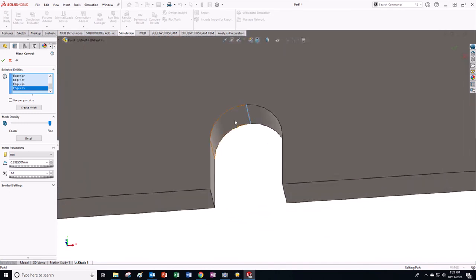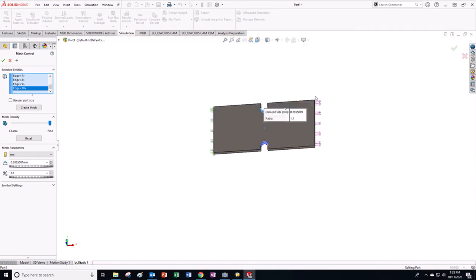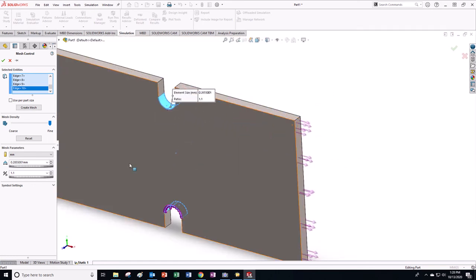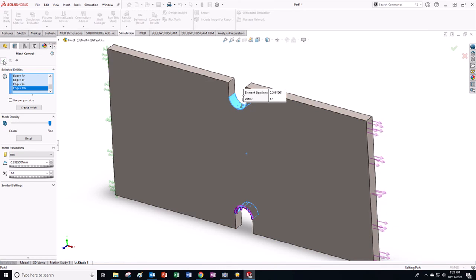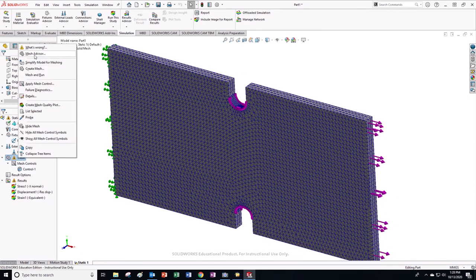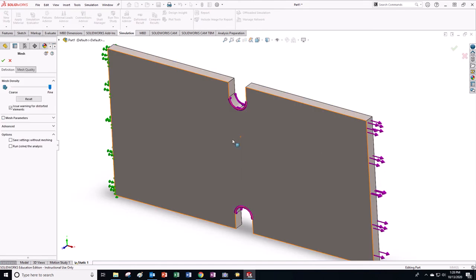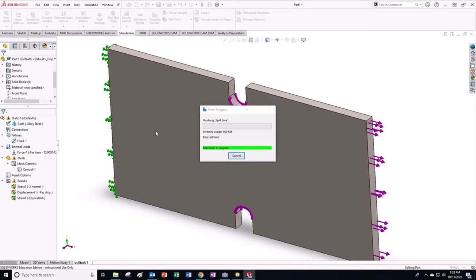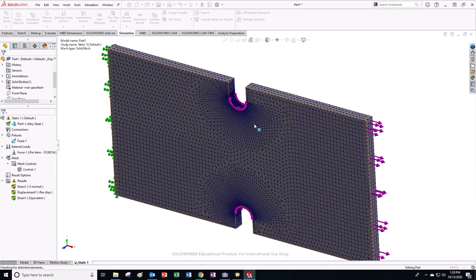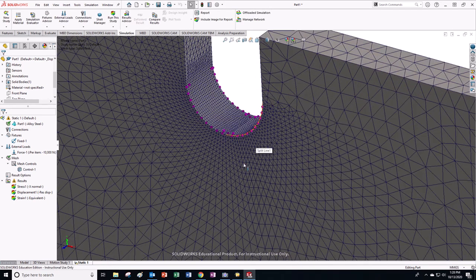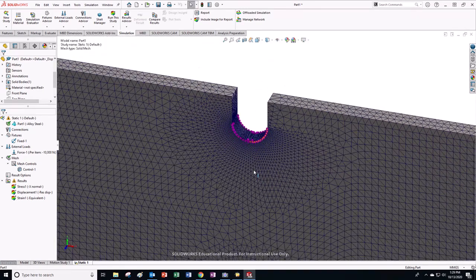By the way, you should really do it on both, but truth be told, you don't have to model something that's symmetric. You don't have to model both sides of the thing. That's another way to really reduce the amount of nodes. You can cut them in half by giving a boundary condition that tells the thing that it's symmetrical about a particular boundary. That's a very common thing to do. Right? And whoop, see, there you go. There's some serious meshing going on right there, right?